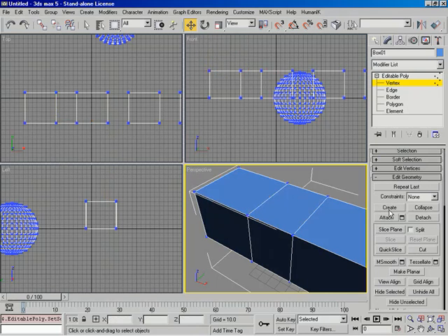Now with create, we can also, while in vertex mode, create isolated vertices that just sit out in space if we wanted to. With edges, which, oh, by the way, if you do that, you can then turn around and go into Polygon and actually turn those into polygons as well. Right. It's a really neat way to quickly start laying out a shape.